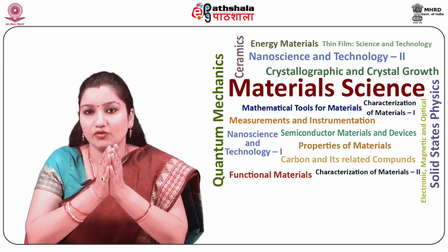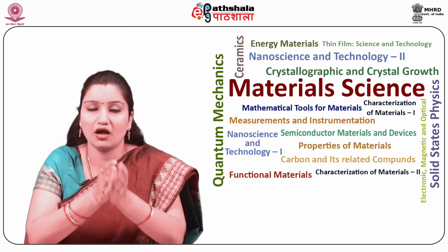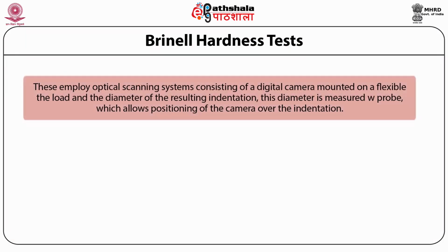Semi-automatic techniques for measuring Brinell hardness are available. These employ optical scanning systems consisting of a digital camera mounted on a flexible probe, which allows positioning of the camera over the indentation.